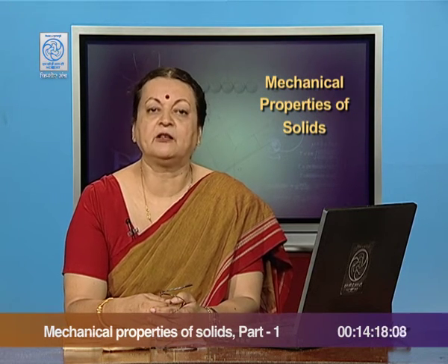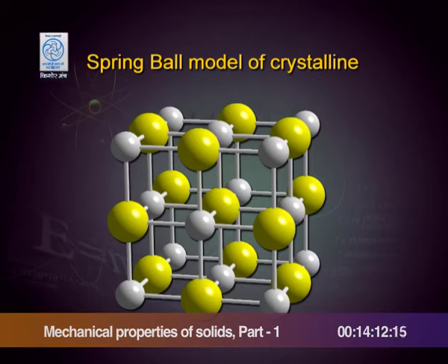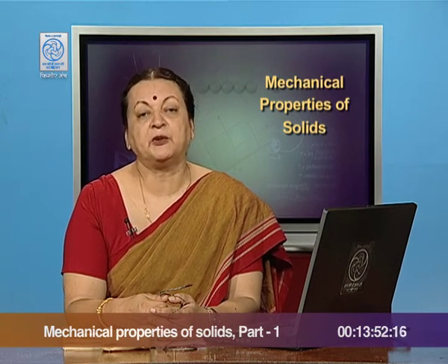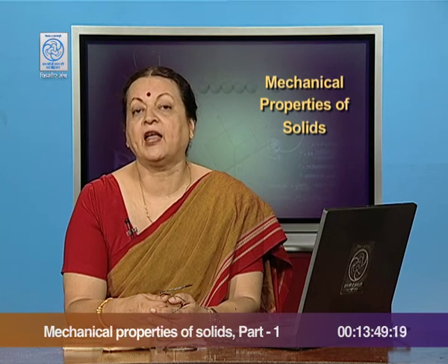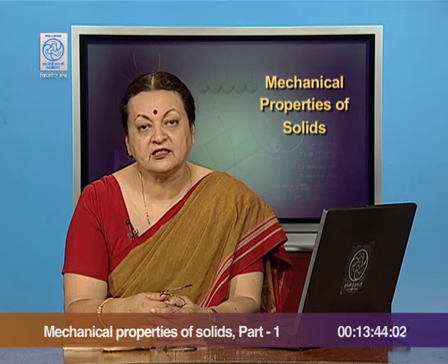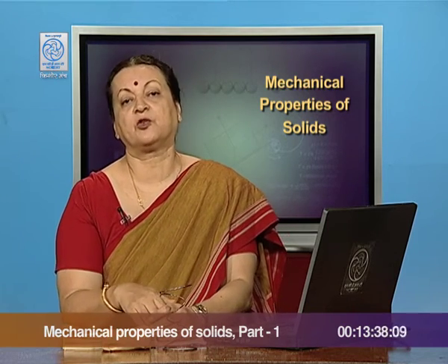To understand this a little better, let us consider a spring and ball model. In this, the ball is the positioning of the atoms and molecules, and the spring is showing the bond lengths. The bond energy would be associated with the energy in the spring. If you were to displace any of these balls, the spring system will try and bring it back to its original position. That means, within the setup against the deforming force, a restoring force is set up, and that is what accounts for elasticity.